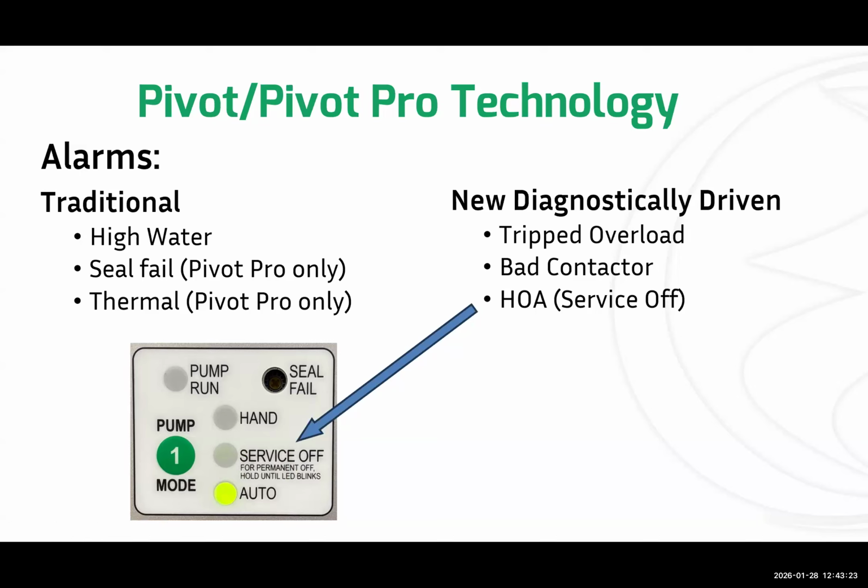If you have your pumps in off, they're not going to run. And you're not going to know that there's a problem historically with control panels. You're not going to know there's a problem until that water builds up, builds up, builds up, and eventually hits the high water alarm. And by that point, the tank's full, it's an emergency, and somebody's got to get out there right away. So that's one of those things we know happens in the real world.